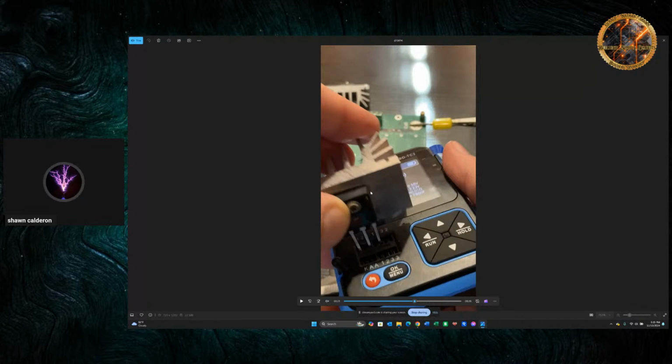And I have a little silicone pad. I know it's a little blurry here. I'm wondering if I can zoom in. No, I can't. So I get these little silicone pads. And the reason is that the conductive grease gets everywhere. And then once it gets everywhere, it lasts forever. In fact, if you stain your clothes with this conductive grease and your house is on fire, the only thing that will survive the fire is that little grease spot on your clothing. That's how tough this grease is. So I don't like it. It's weird because nobody mentions this in any of the videos I've seen on cooling down your components. But get these little pads and life is easy.